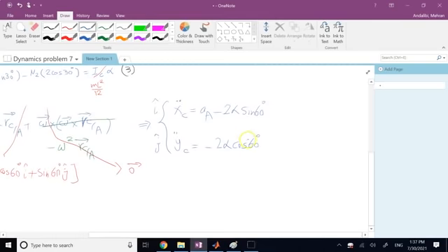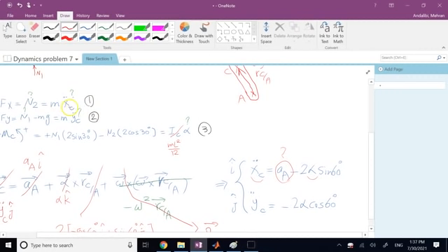Now here I got two equations, but one of them, which gives me x double dot of c, the problem with this equation is it relates two of my existing unknowns, x double dot c and alpha together. The problem is it brings one extra unknown, a of a, which I don't know. So if I want to use this one as well, it gives me one equation but one unknown, which means basically it's not doing anything, because I'm only looking into equations that can help me solve this system of 5 unknowns and 3 equations. I want 2 extra equations without without bringing in a new unknown.